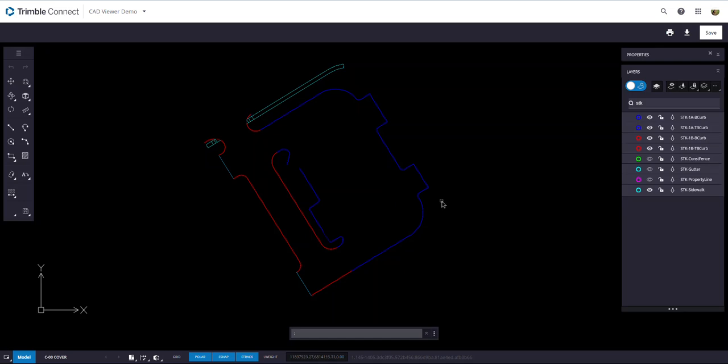And so now we want to join these lines. We're going to use a little bit different command called Polyline Edit and Multiple. But to do that, let's turn off the sidewalk. So we'll turn that off. And then let's go ahead and turn off the bottom of curb for now, leaving just the curb, the 1A curb. All right. So what we're going to do is we're going to type in command Polyline Edit or pedit.